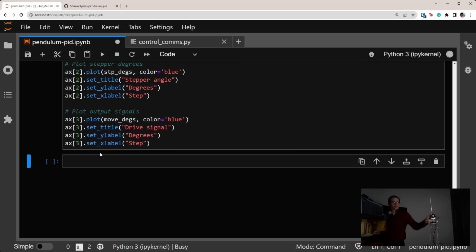In many cases, a PI controller is enough. However, we can often tune the Kd term to remove some of that overshoot. With Kp, Ki, and Kd set, we have a fully tuned system. Here, the output quickly approaches the set point without overshooting.